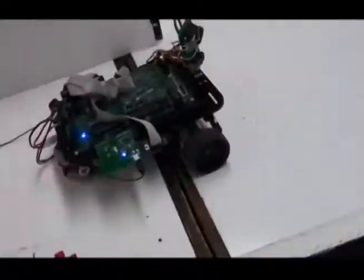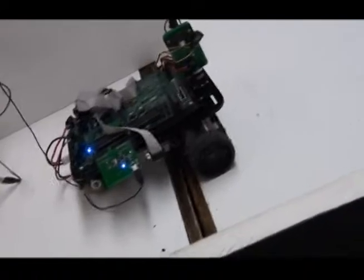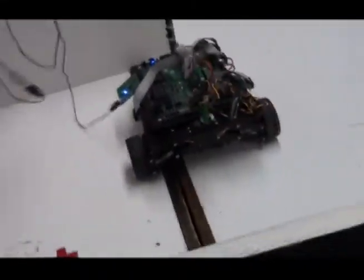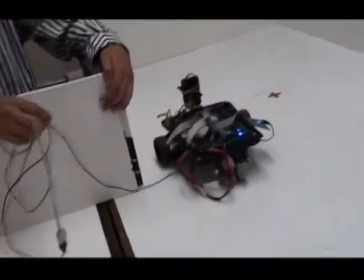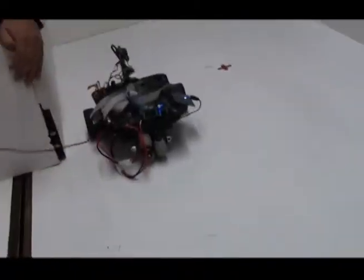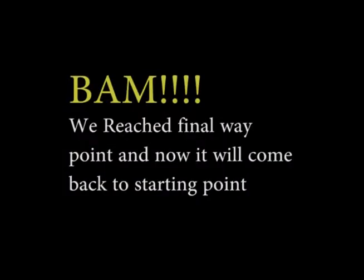Alright. So I'm going to talk about the difference between the actual robot and the virtual robot. Well, the virtual robot is a perfect world, so odometry works perfectly and the IR sensor works perfectly. But in the real world, the IR sensor gives you glitches. The distance suddenly gets shorter, and sometimes the distance suddenly gets bigger, and because of that glitch we need to add a filter.